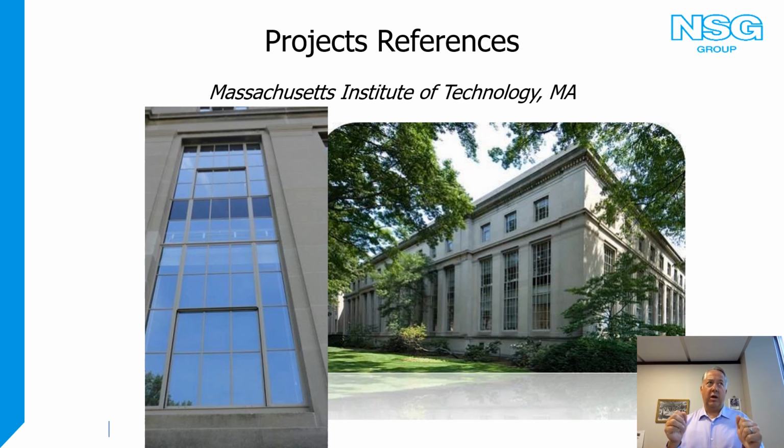And after 3 years, they went with replacement non-thermally broken metal sash with VIG as the true divided light glazing, because they said that had the least impact on the aesthetics of the building. It kept truest to the original design, but it also got them the energy performance and the potential longevity that they were looking for. It was the only product that they felt could probably get them a 50-year life cycle, and the comfort and energy efficiency that they were targeting.